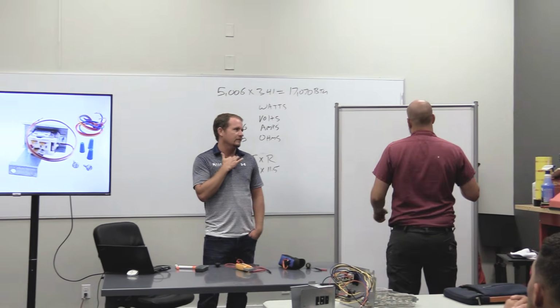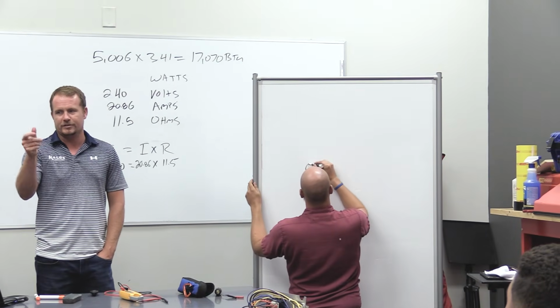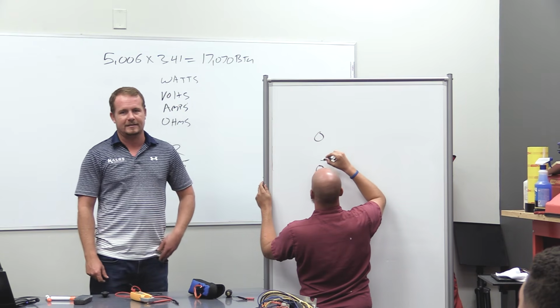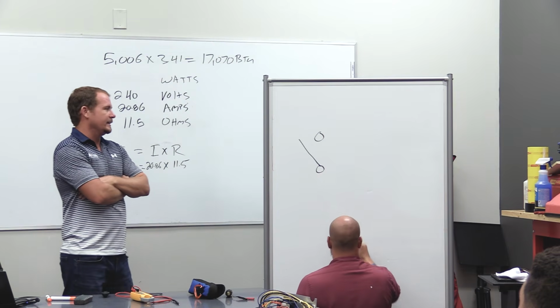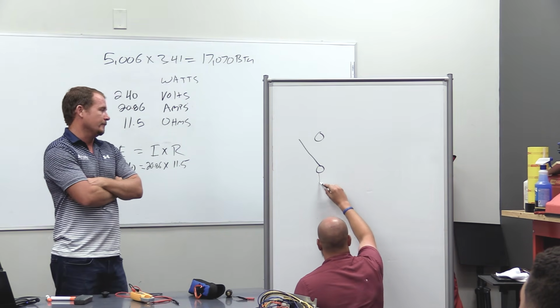It doesn't matter. Okay. So in many cases, you're going to use a universal control that you just set the dial, and sometimes it's just going to be a snap action disc that's automatically set to 40 degrees. But the general idea is when it gets below 40 degrees, it's going to close and allow the heat strips to come on.